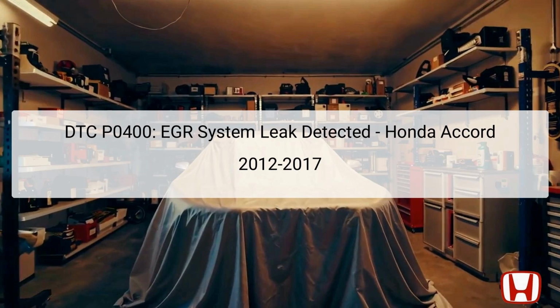address. Before starting the troubleshooting process, it's essential to gather all freeze frame data and snapshot information from the onboard diagnostics. This information gives insights into the vehicle's conditions when the DTC was set, aiding in accurate diagnosis.